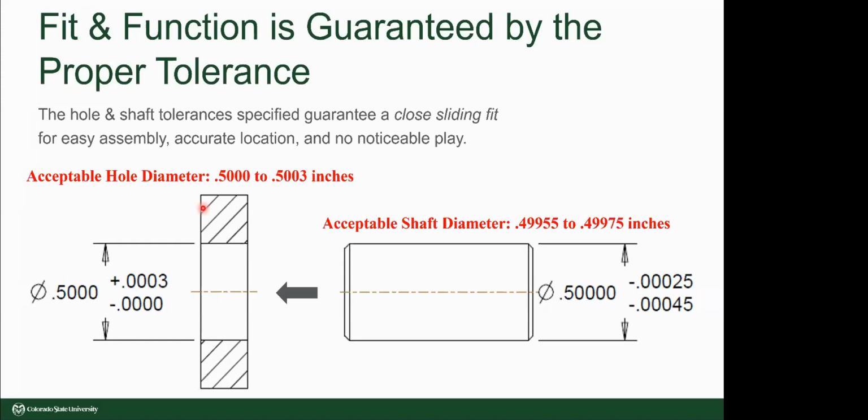So in other words, the purpose of this shaft is to align the part with the hole to another third part that's not shown. And knowing this, tolerances can now be selected from a standard for fits.